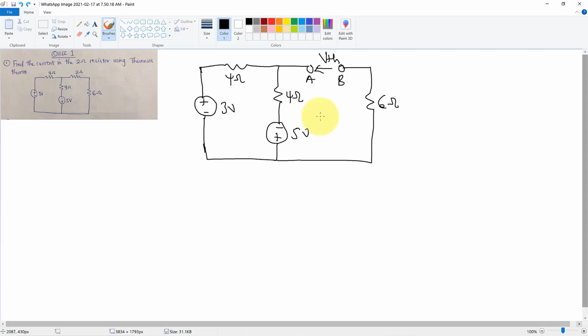Now, after assigning that particular voltage, the Thevenin's voltage, in the circuit, we are supposed to find that VTH, but we can see that no current is acting in this part of the circuit at the moment. However, we can use this part of the circuit to find the current because there is a closed loop over here. So if we assign a current I produced by this loop, we can now choose this loop to find our current I.